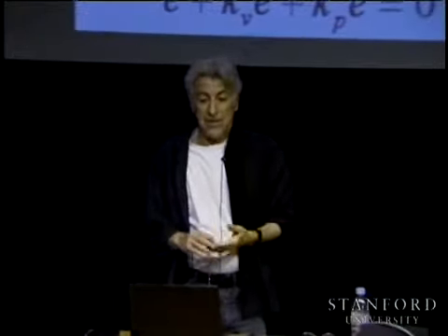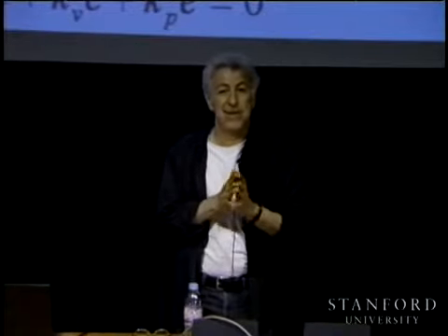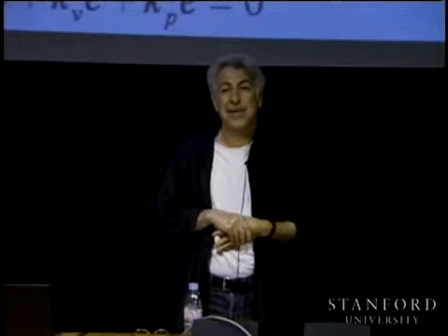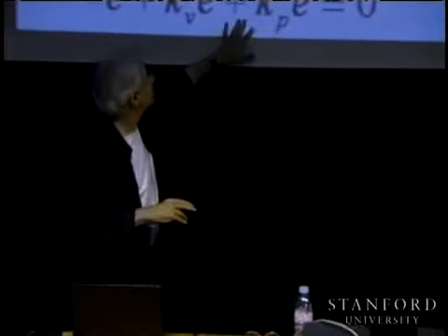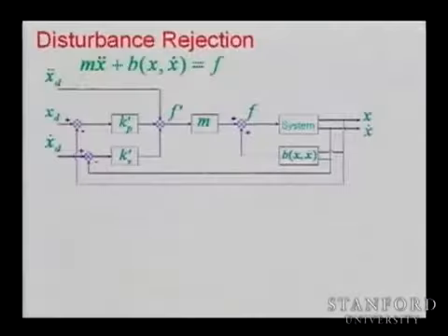Okay. So now we have to make sure that we can do this with the whole robot, and we have to make sure that this controller could work with those gains that we are trying to achieve. And we start analyzing the system. So let's imagine that I designed the compensation with the B hat. I'm sorry, they are not appearing as hats, but this is B hat and M hat. And I get everything over there. But then now we are talking about the real system.